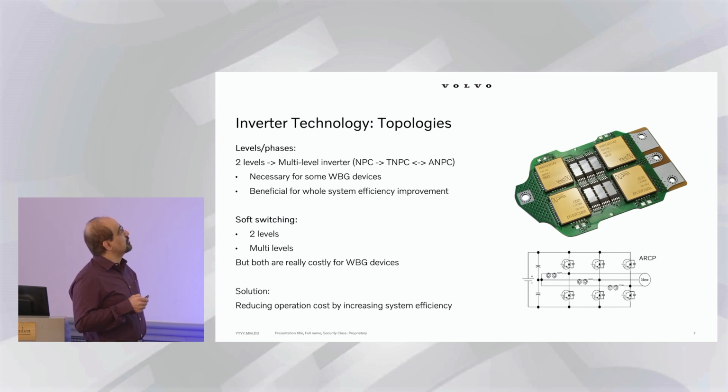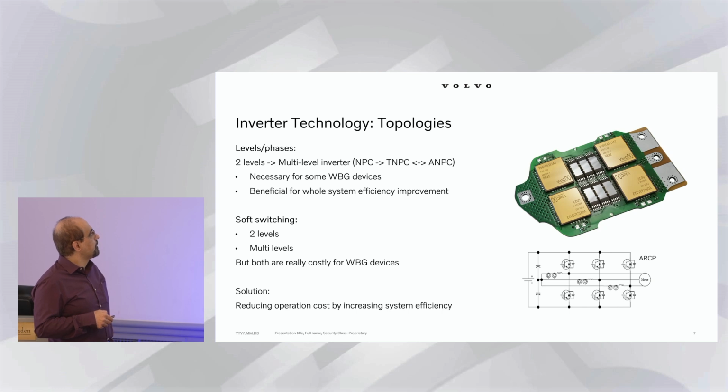We see that multi-level can benefit system efficiency, but it is not only related to wide bandgap devices, it is related to two-level too. A wide bandgap device doesn't let us select any topology we like. We have to combine wide bandgap with, for example, other devices, and soft switching as well, either in two-level or multi-level.